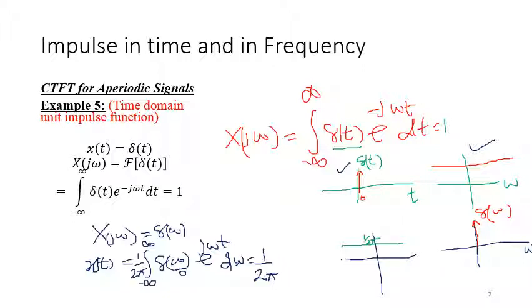So this is time. So if we have impulse in frequency, this is its time domain. So this basically signifies that time and frequency are reciprocal of each other, right? So if something exists for a very, very brief time, it exists in all frequencies, and if something exists on some particular frequency, then if we talk about the time domain counterpart, it exists on all times.